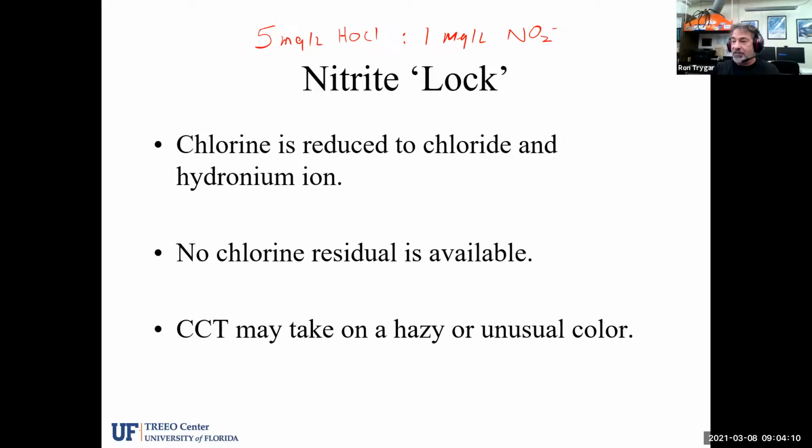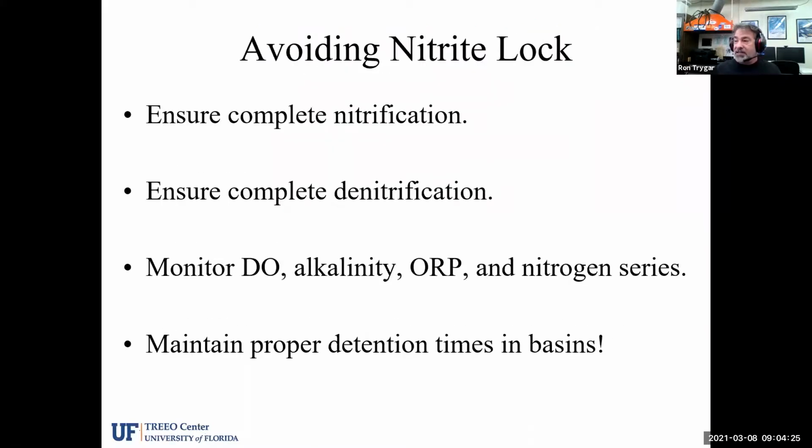And many operators see this happen during certain times of the day. A lot of times it's because we're flowing through the process really quickly during the peak load of the day, and we just don't have enough time in the aeration basins to fully nitrify. So that's what this slide says. How do we avoid nitrite lock? You want to avoid nitrite lock, make sure that you ensure complete nitrification. That is one of the leading causes of this.